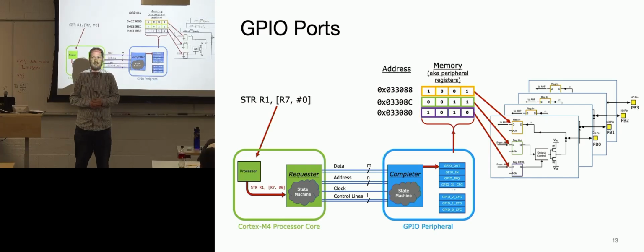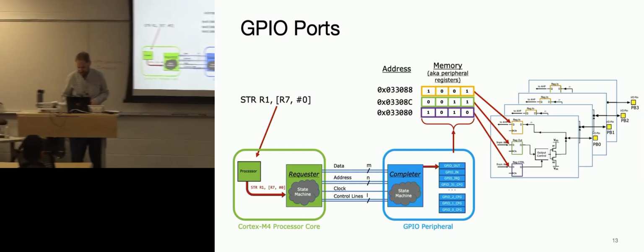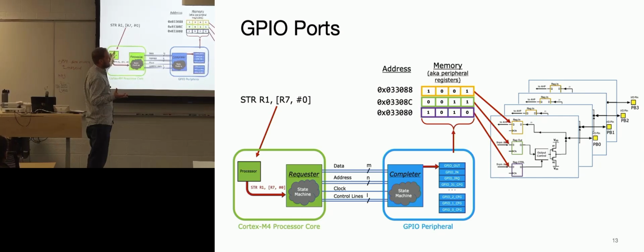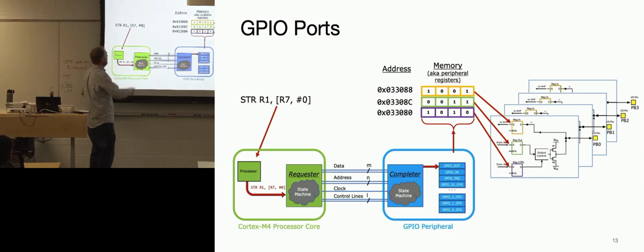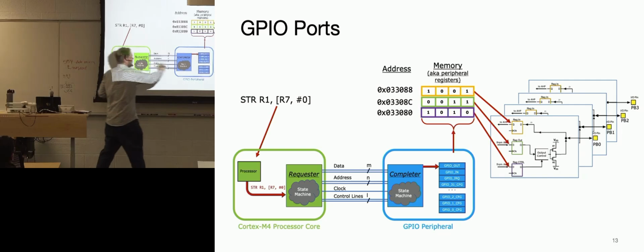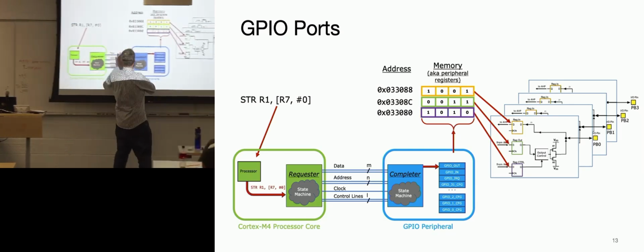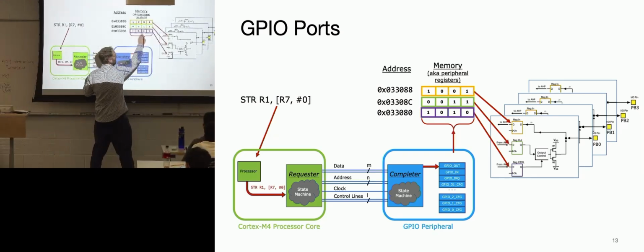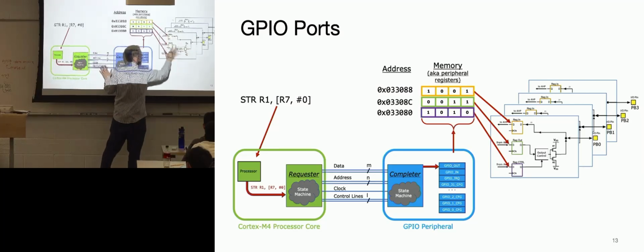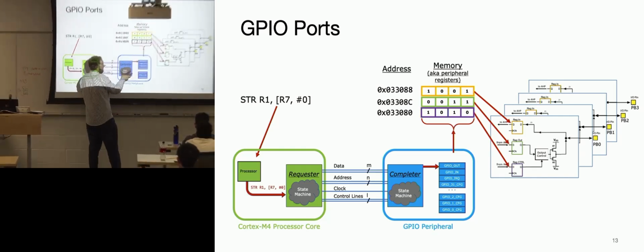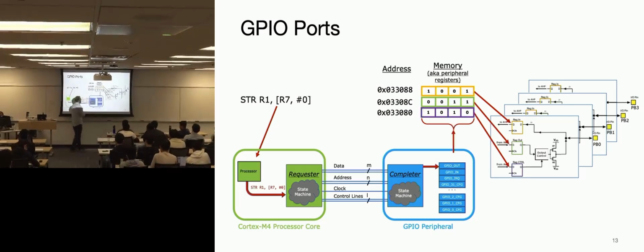Any more questions? Okay. So I think this is probably the crux of the first half of this class. This is exam 1 essentially, right? Understanding how data flows through here. This data is going to cause these lines to go high and low. Which of these lines are going to go high and low when you do this? These lines going high or low cause bits over here to go high or low and control some tasks. Typically, you guys are writing some sort of state machine here, or some combinational logic which manipulates something that will talk to the external world.